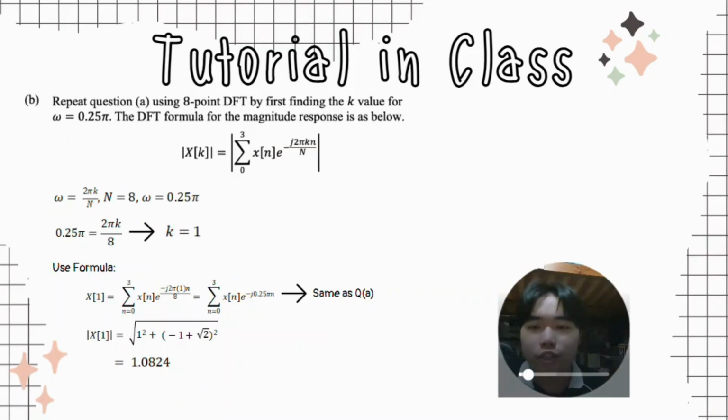Next, tutorial question B: repeat question A using the N-point DFT, where the capital N equals 8. Find the k value for omega equals 0.25 pi with the given DFT formula. To find the k value, we need to use omega equals 2 pi k over N. Substituting the values, k equals 1, and substituting all the values back into the DFT formula, we can get the same formula as question A, so we directly get 1.0824 for the magnitude response.